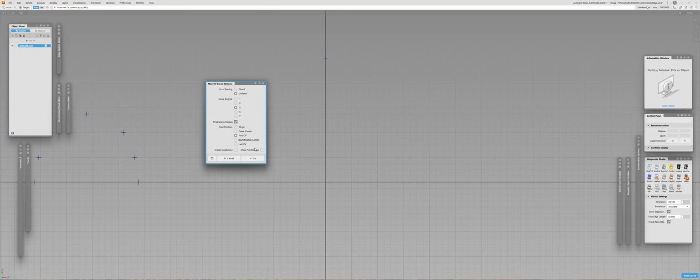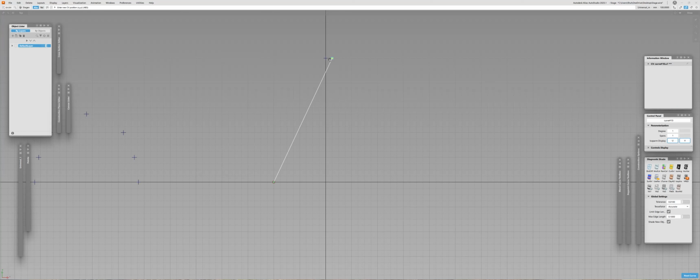So I'll open up my CV curve tool and I will use 3 degrees with uniform knot spacing. We will tackle this. This is pretty important. And by the way, this value, the uniform, is set by default, so you don't need to switch anything. And I will just create a parabola.